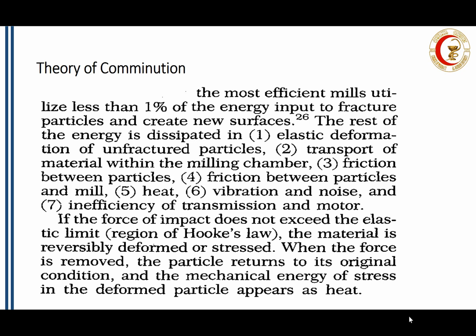Second, energy is expended in the transport of the material within the milling chamber. In the milling chamber, we introduce a large amount of material, so when we begin the milling process, moving this material around will require energy. Also, we have friction between particles and friction between particles and the mill.